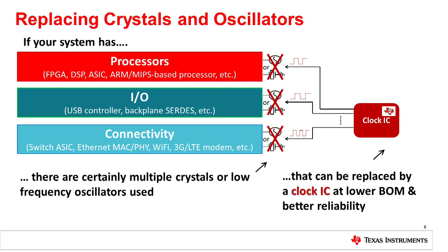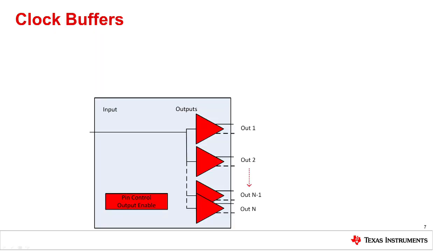When there's a need for multiple copies of a single frequency, such as 4 times at 25 MHz, or maybe you need 8 signals which are of 100 MHz clock frequencies, then a clock buffer may be a better fit than multiple XOs. A clock buffer, also referred to as a fan-out, takes an input and fans out copies of the input frequency to multiple outputs. Clock buffers can typically have 1 to n outputs, where n is 2, up to 1 to 12 or even 1 to 20.